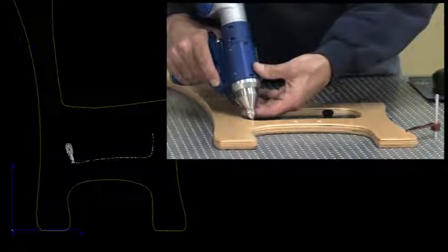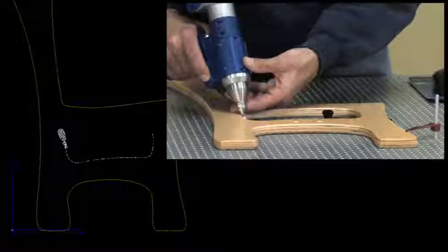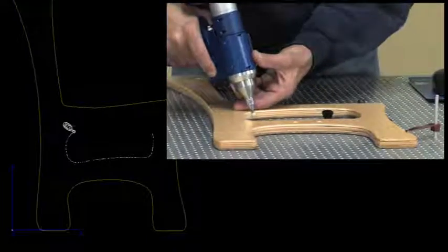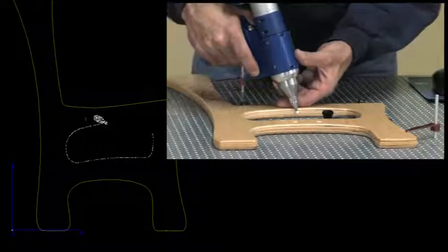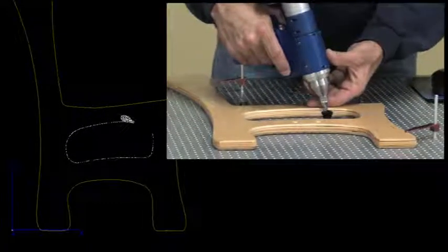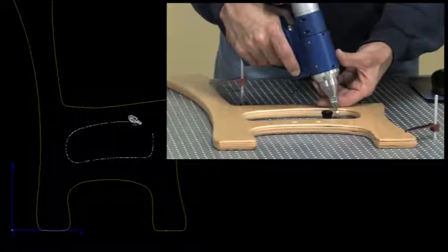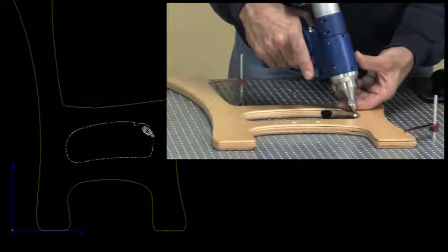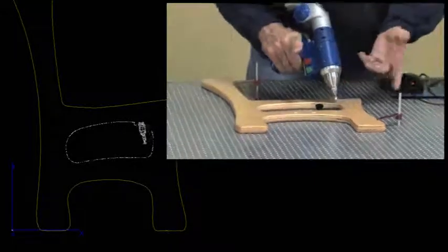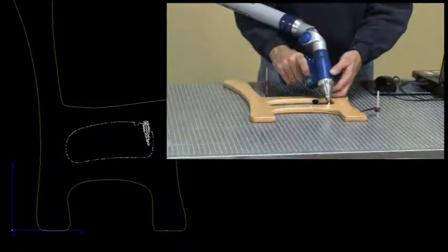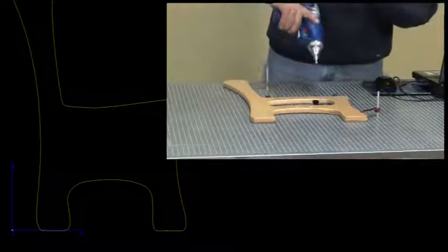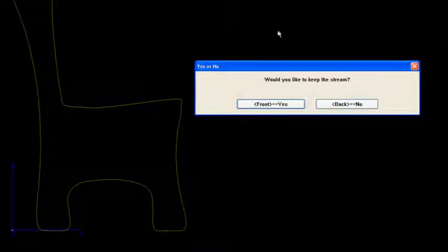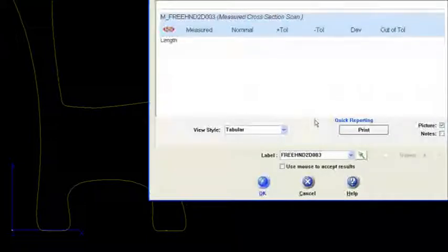And I'm holding down the green button as I'm making this path around here. Oh, and say, yep, had a fixture piece there I had to work my way around. And there's about where I started, so I'll stop right there. I'll let go of the green button, and then I'll hit the red button to compensate, or to save that stream. And then back into the SAT file here, I'm going to say yes to that stream, and then here it saves the results of that stream.